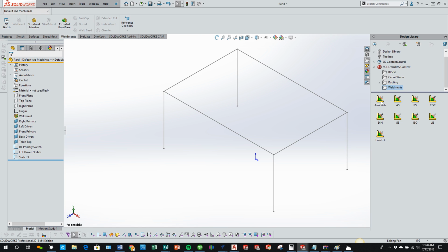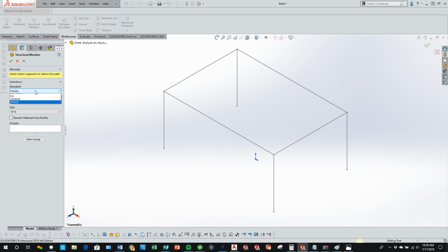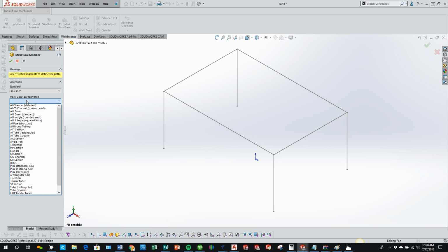And so as you see here, as I'm hovering over it, the little tech tip that comes up says, hey, if you want to use this, you need to hold down Control and click, and you'll download the zip file. Once that is done, you'll then tell SOLIDWORKS to look to this location, and from there on out, whenever you select structural member, you will see that zipped folder that's downloaded. And now you've got a plethora of different profiles to pick from.